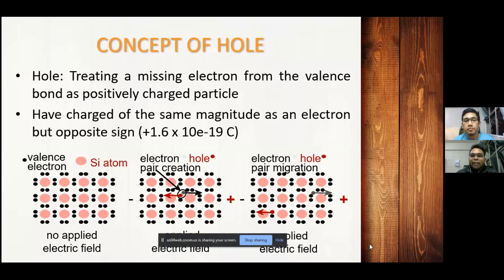In an intrinsic semiconductor, for every electron excited into the conduction band, there is left behind a missing electron in one of the covalent bonds, or in the band scheme, a vacant electron state in the valence band. Under the influence of an electric field, the position of the missing electron within the crystalline lattice may be thought of as moving by the motion of other valence electrons that rapidly fill in the incomplete bond.